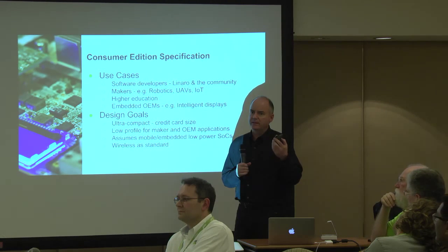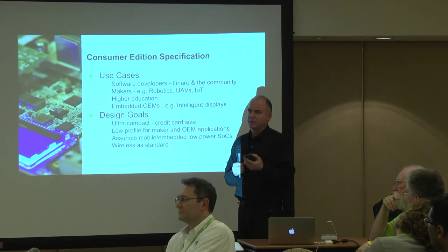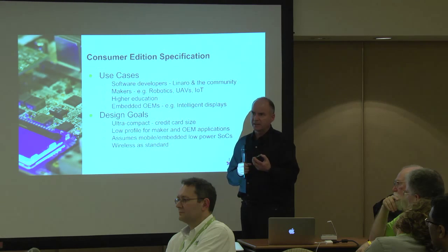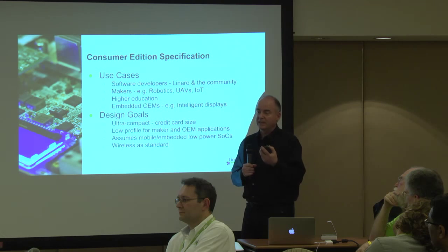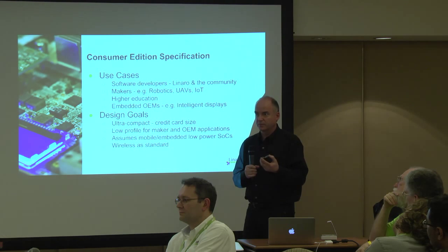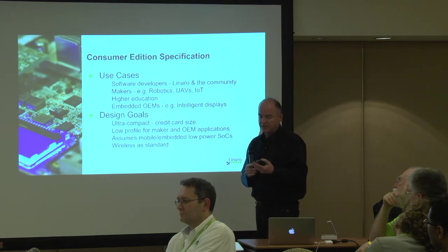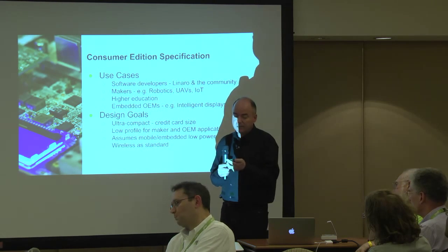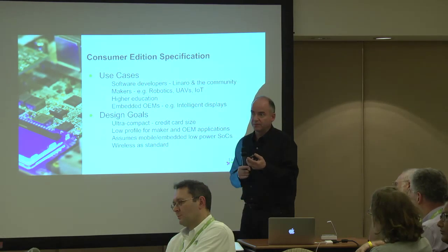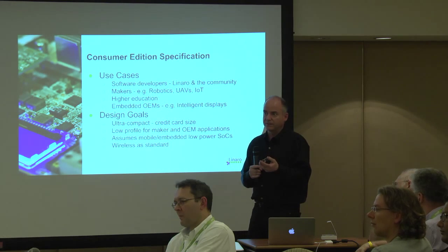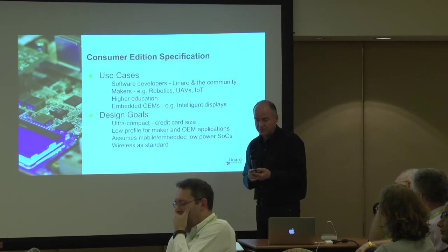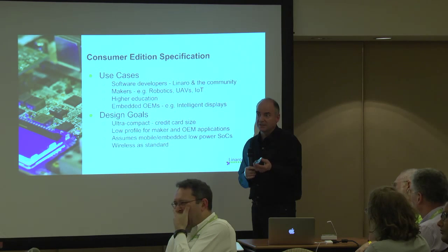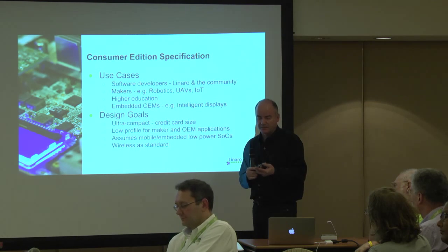And because of the way the HiSilicon SoC worked, we actually populated those boards with a debug header that you will never need, even if you brick the board, once we've got our own bootloader on it, because you can restore the board through fastboot onto the micro USB. So the production boards are not populated with that connector. That connector was only for the initial bring up for debugging purposes. You can put it in if you want. We've documented it. The holes are still there, so you can add it if you want.